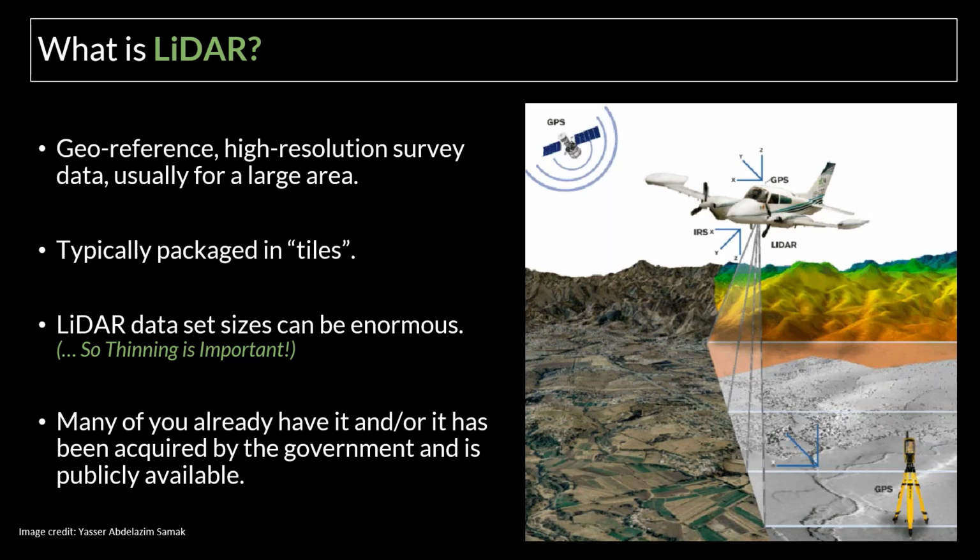So it is typically packaged in what we call tiles. And the size of those tiles, especially if you have to use multiple of them, can mean that LiDAR data sets are enormous. And so when working with these super high resolution survey data sets, it's really important to make sure you are managing and controlling how many points are included. And hopefully Matt's got this on his agenda for today, but the idea of thinning your data is so important in keeping that LiDAR data set to be a manageable size.